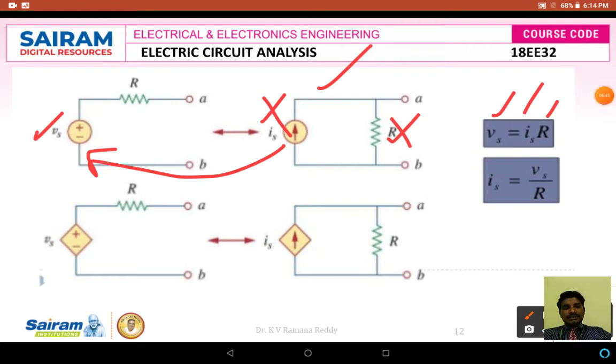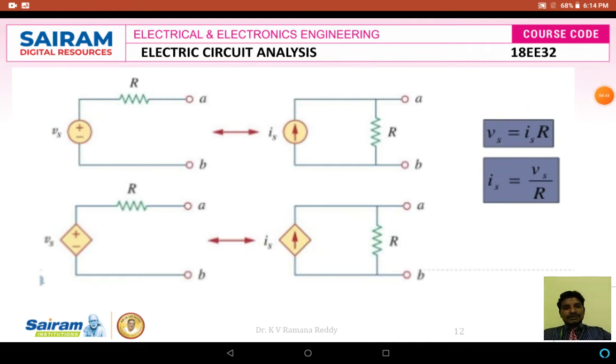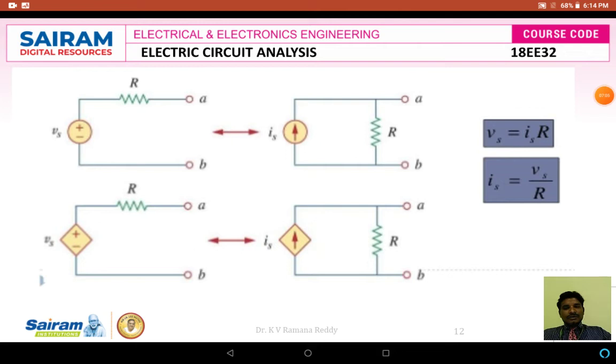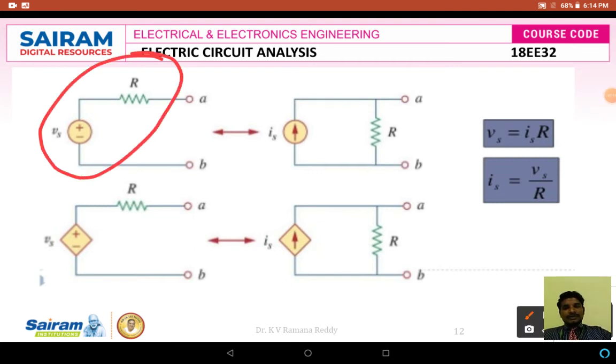And how do we shift the internal resistance of the current source to the internal resistance of the voltage source? The internal resistance of the current source, that is R, is shifted to the internal resistance of the voltage source, that is R. Here the R value is the same in both, but only the way it is connected to the source differs. Here it is connected in series, that is the independent voltage source and its internal resistance. Here it is connected in parallel to the independent current source and its internal resistance.